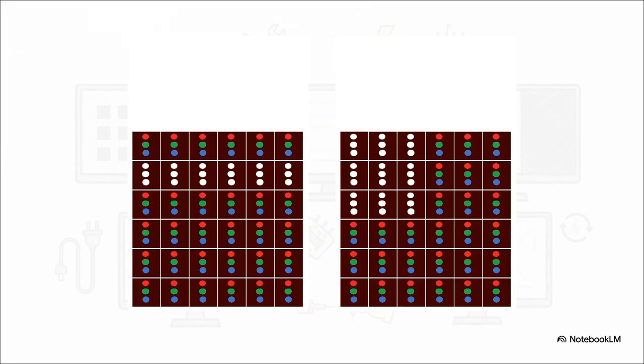If you've got a missing vertical column, your culprit is a driver IC fault. But if you're missing a horizontal row, you are looking at a 74HC245 or a 4953 logic buffer chip fault. In both of these scenarios, your fix is to check for short circuits, replace those specific integrated circuits, and repair any broken traces with the jump wire.